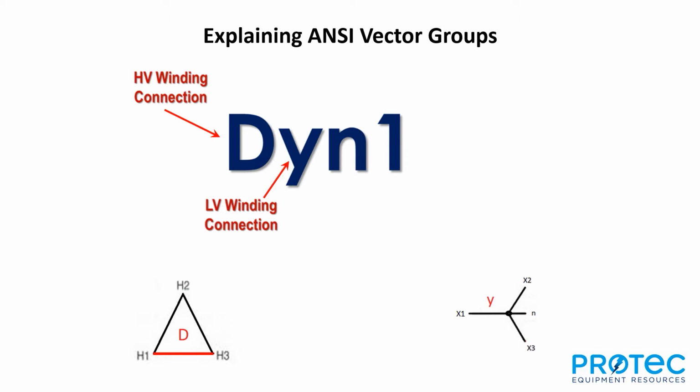Again, it's identified by the fact that one end of each of the phase windings is tied to a neutral or a common point. And by the way, that Y could be turned right side up, upside down, pointing the other direction. However it may be configured, it's still a Y because one end of that phase winding is always tied to a common.